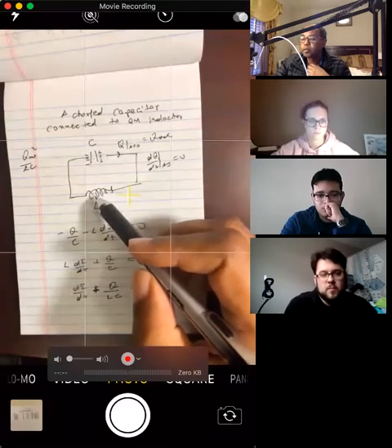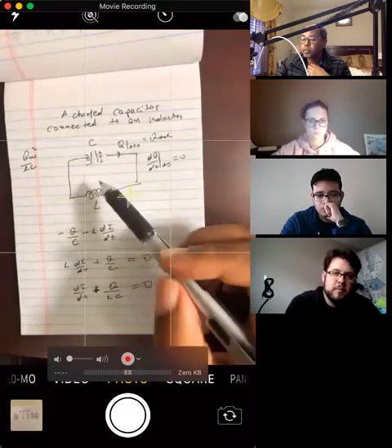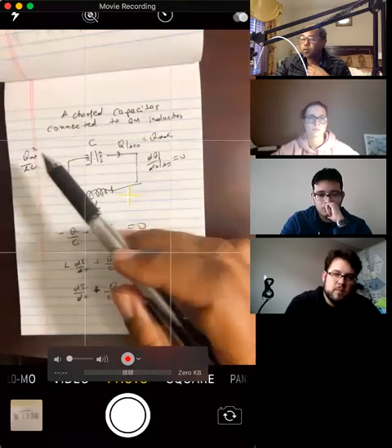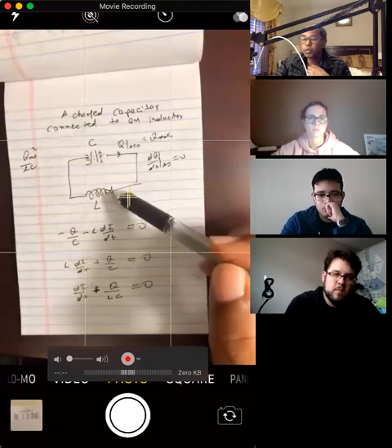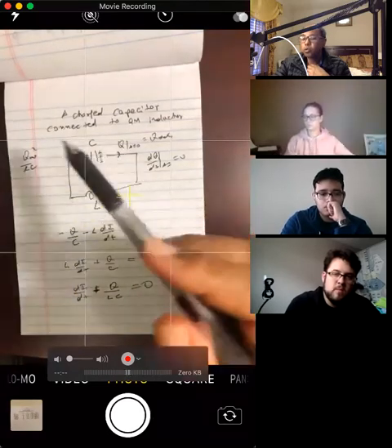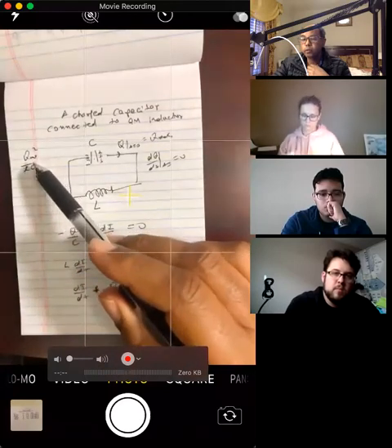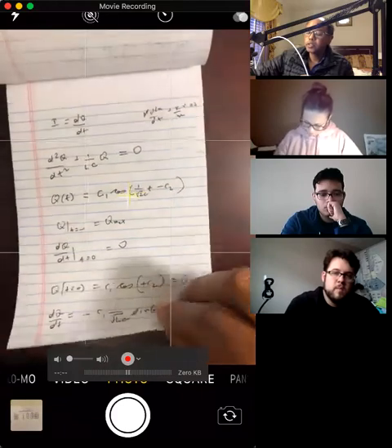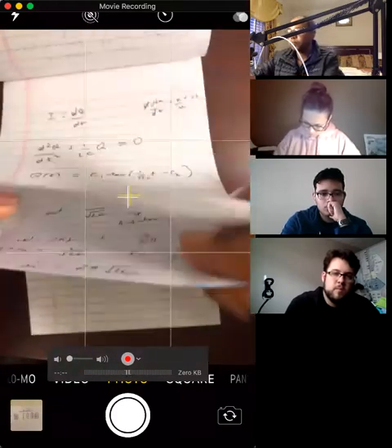So you've got this energy plus zero magnetic energy. This is the initial energy you have. But the energy is a constant, so electric energy will be converted to magnetic energy and back to electrical energy, but it's always equal to this value. So this constant actually equals Q max squared over 2C.